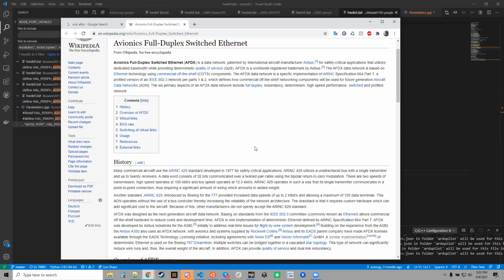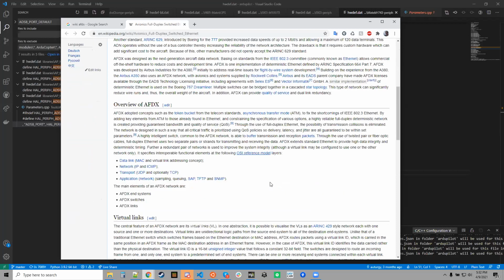It's just UDP IP. It's as simple as it gets. It's at the protocol level, and it's statically configured, so you don't really need a full TCP/IP stack with ports and all of that stuff. I can't imagine it's any more complicated than MAVLink at the code level. But go big or go home. Why have one stack when you can have them all? You could technically then hook up a ring laser gyro to an ArduPilot flight controller or something like that, which sounds outrageous, but maybe down the road that's the sort of thing people would want to look at doing.